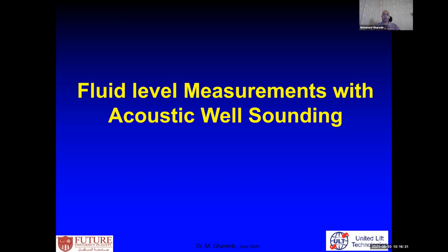Really, there is also a lot of research on this point. Some people use the downhole card to calculate the well production, how much downhole displacement. Some other people use it to calculate the pump intake pressure, and consequently the bottom hole flowing pressure, and from the production rate it is even used to construct the well inflow.